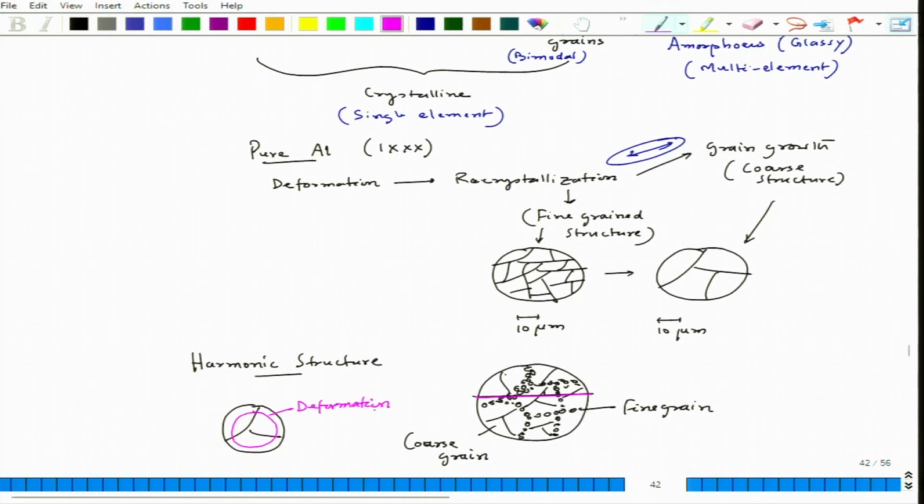Fine. So, if you sinter two objects, two powders like this, say another powder with a surface deformation, now when they sinter, and sintering is done at high temperature around 800 to 900 degrees Celsius, in case of steel we can go up to that temperature. So, when it sinters, that time this deformed zone will get recrystallized.